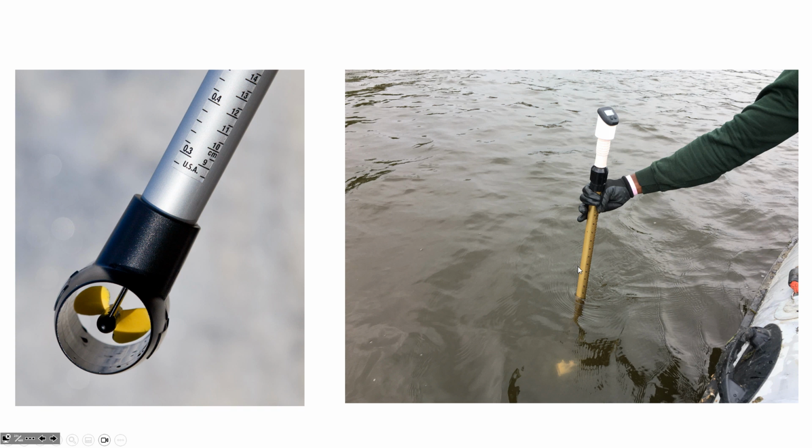And way back in fluid mechanics, you learned the idea that when you've got water flowing through a channel, so let's say here's the bottom of a channel, and here's the water, and it's flowing this way, at the bottom of the channel where the water's in contact with the stationary solid material, the water velocity is 0 because of the no slip condition. And so there's no velocity there, but it's a little bit faster up above and faster. The further away you get from that boundary, the velocity is increasing. And so there's a velocity profile.